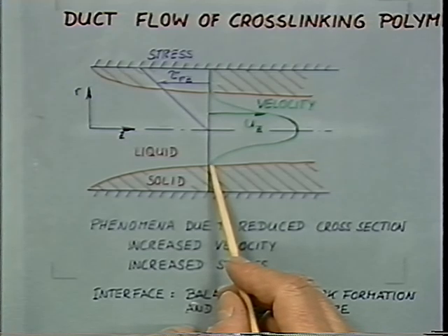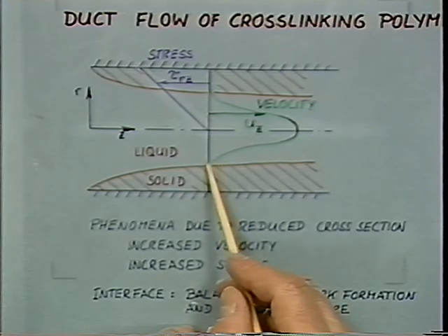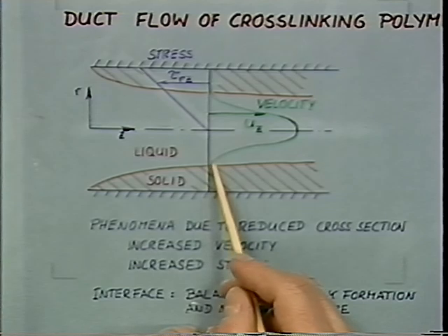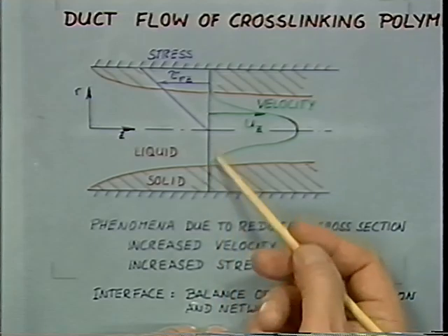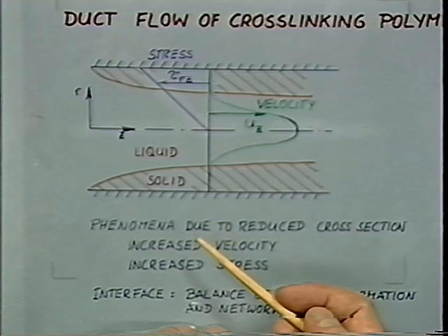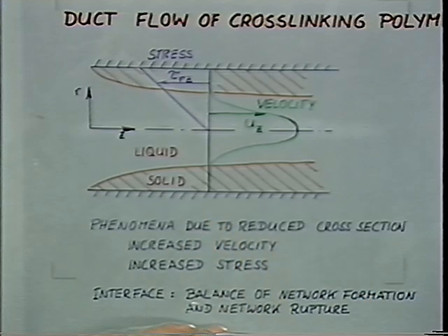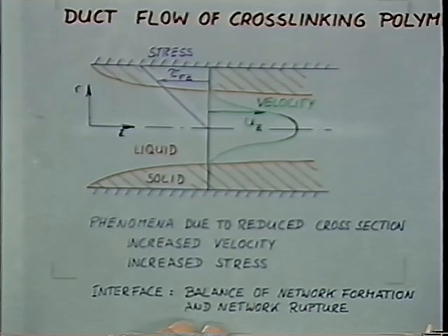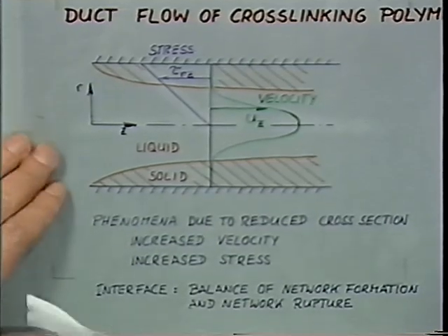It's a very soft gel still at that residence time. And then the stress level is large enough to break the system, and the further build-up of this layer will be prohibited. But as soon as you stop your process, you are done. You have to open the die and clean everything. So that would be interesting to model if we know more about the crosslinking systems during flow.